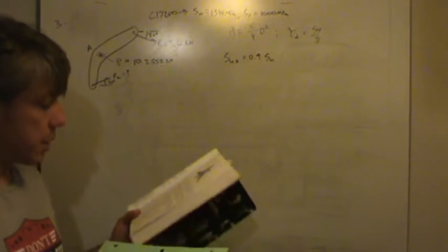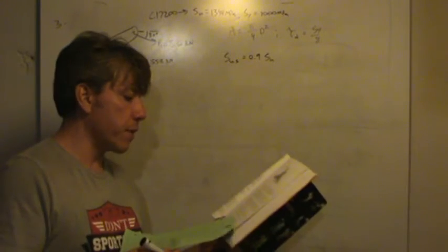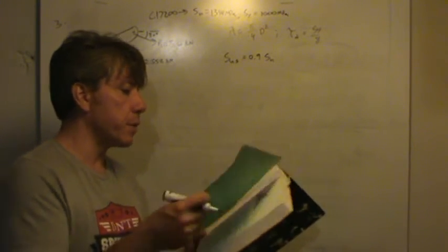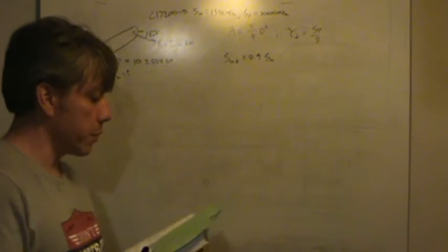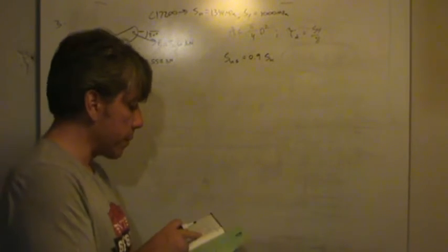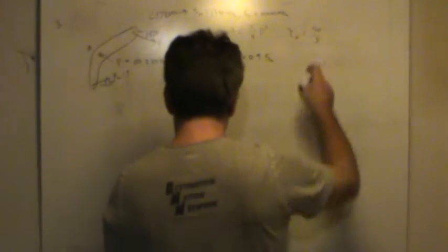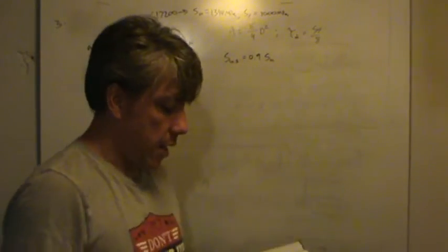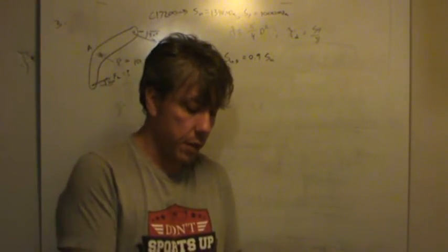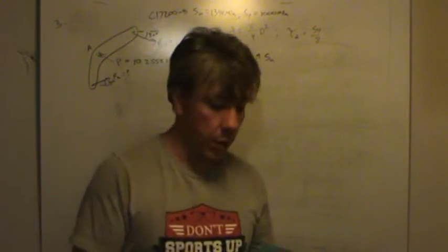But then you notice that it says see table 3-8 just above for guidelines for design factors when ductile materials are used. So if you go over to the ductile materials, you'll see that for repeated loads, which is what we've got described here, the design shear stress should be the yield divided by 8. And so we're in somewhat of a quandary about which one to use because 4% elongation is pretty close to our cutoff of 5. On the other hand, it's below. And so what do you do here?